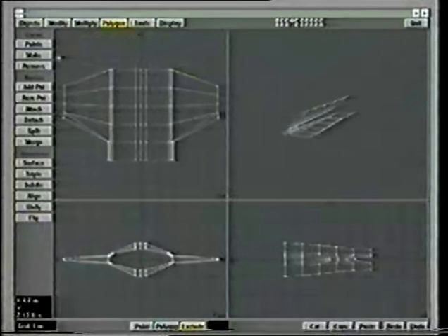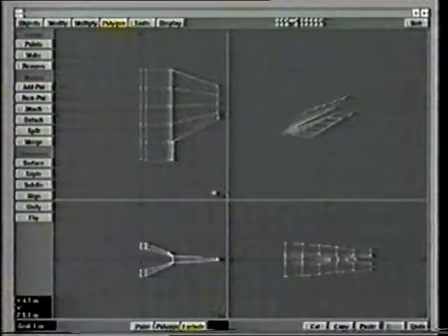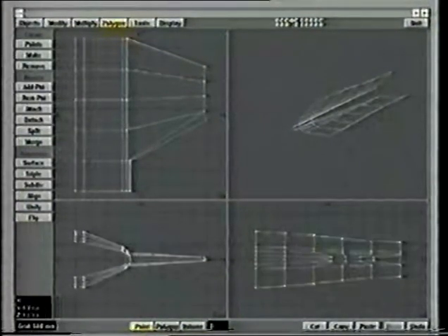The best way to do this is to cut the whole assembly in half. As we've got a symmetry on either side of the z-axis here, I can just work on one side only and then just mirror it and merge the points. Therefore it's saving you an awful lot of time and trouble. So let's auto center this and select these points in order at the trailing edge of the wing and create a polygon there. Check, see which way it's facing, the right way, so that's good.